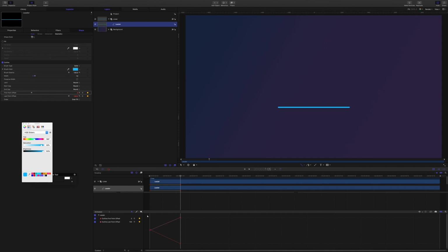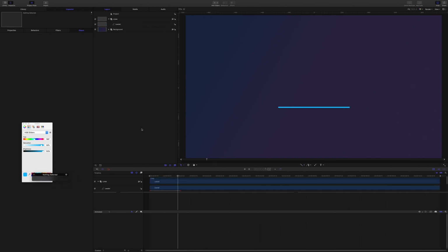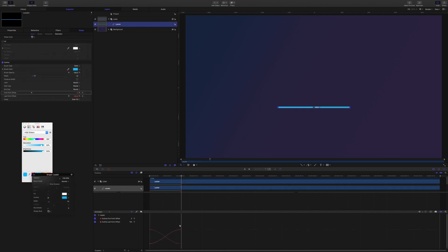Okay, so I'm going to grab these curves here and right click and set the interpolation to a Bezier, and we have this ease in and ease out effect now, but I want to reduce that for each curve. Like this, just in keeping with the After Effects graphic.